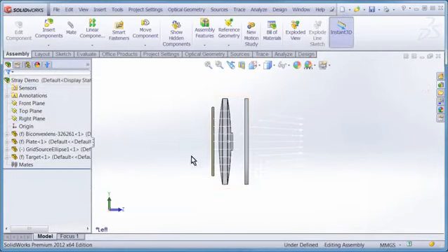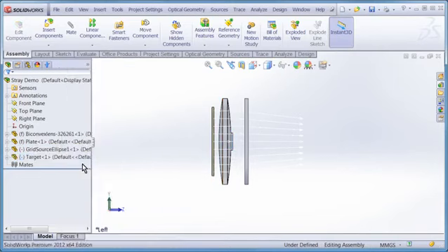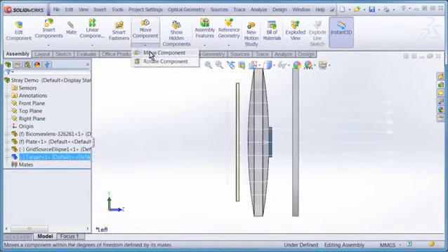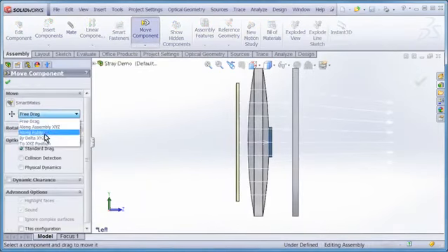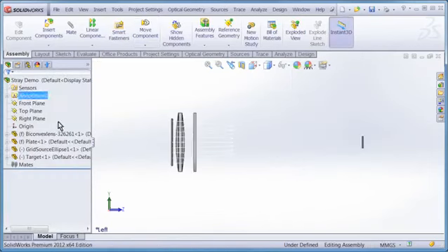Now, when I did that, the surface was positioned relative to the origin. So what I'm going to do is allow that position to float, and using the Move option, I will move it to the desired Z position. Click Apply, and then OK. Now if we zoom back out, we see our target at its desired location.